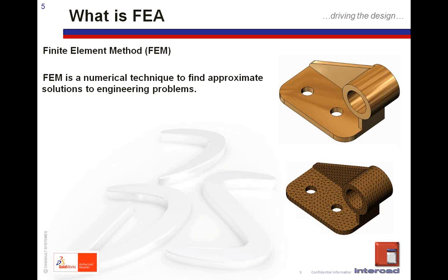At the end of the computations, it gives displacements, and using these displacements, the program calculates strains, stresses, and factor of safety distribution on your structure. We can get pretty good results with finite element analysis if we can construct a realistic finite element model. But as we move away from real case, the result of the finite element analysis would not be accurate. So garbage in, garbage out.